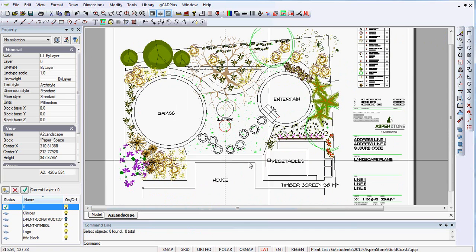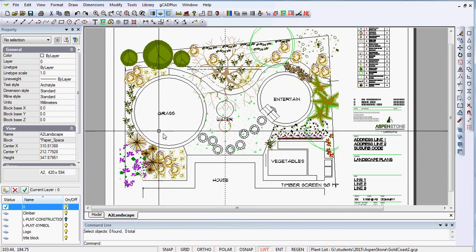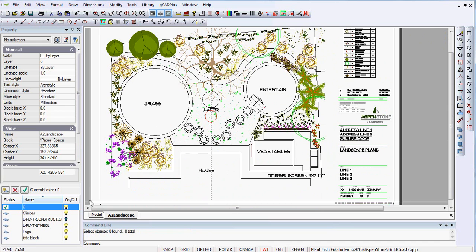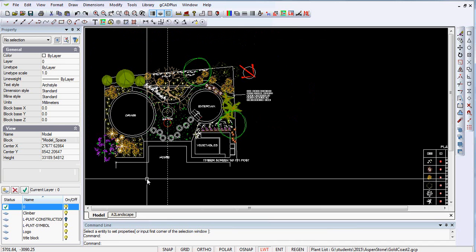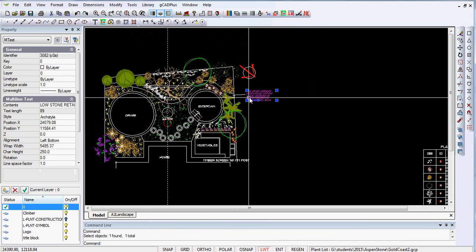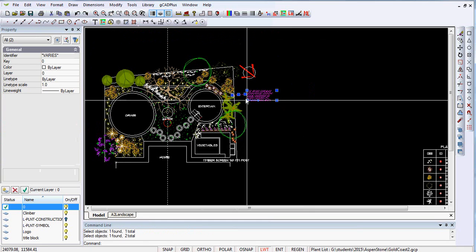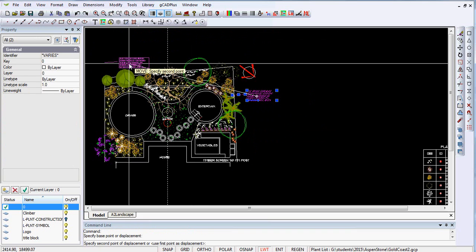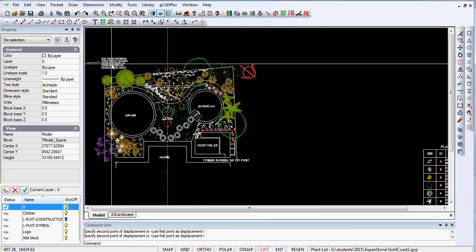We go into here. Now our drawing is showing. What we're missing is that text over there. So you could just simply pick that text up and move it and put it up in the top left. I don't want to change the scale in that floating viewport at the moment because it all looks fine. So I'm selecting those. I'll move them from there and put them up there.